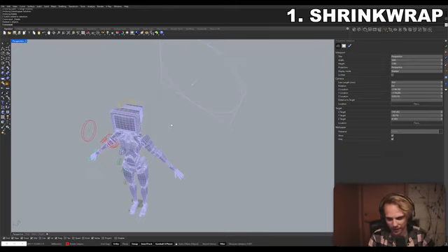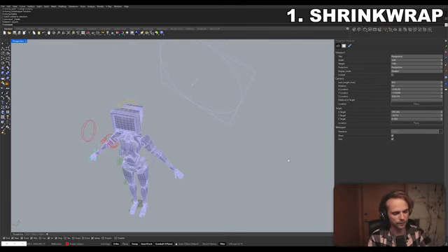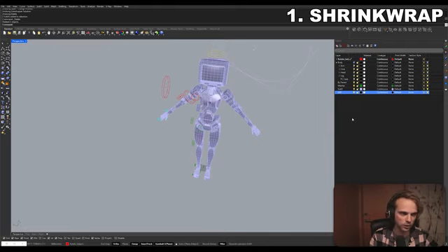And that is called shrink wrap. Surprise, surprise. Shrink wrap is a tool that makes any messed up geometry that you might have into 3D printable solid mesh. And then with additional tools, you can convert it into SubD with quad remesh and so on. But the main purpose is watertight solid mesh. Perfect for the FEA analysis, the stress analysis and so on, or wind analysis, or for 3D printing. And for us architects, 3D printing is the key place where this is going to be used.